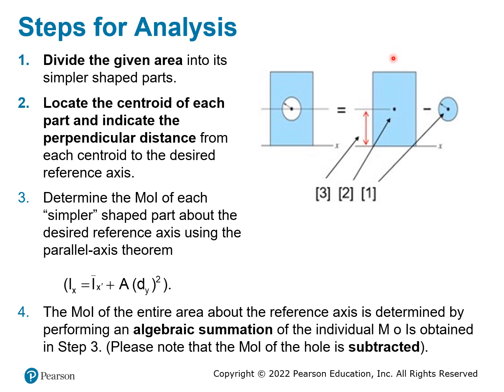It will give you the Ix and Iy. You can find the Ix and Iy of this one as well. And then you can find the total centroid Ix. But if you're looking at this axis, then you have to use the parallel axis method to find that. So this whole process, everything here is just simply adding or subtracting numbers. There's no vector. You do algebraic summation, so it's a very simple process. You just need to do some examples.